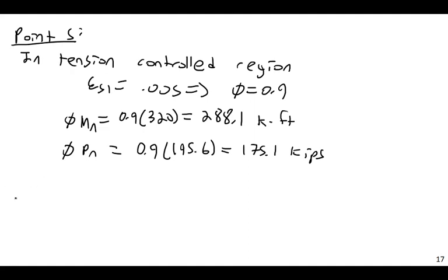Previously we calculated the reduced allowable capacity just based on that 80% reduction factor. There's a thing in the code that says you can't have an axial capacity greater than 80% of the overall capacity. So we've already calculated that line, and now we need to factor it by a design factor, a phi factor, in order to calculate a design value for that line.